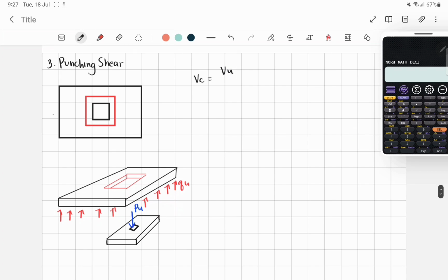Okay? So to get the punching shear stress, again, since shear yung usapan natin, that is VU over the shearing area. But ano nga ba yung VU natin dyan? Okay? So we can select from these two members to use. Kasi sa two members na to, when we analyze them or get our shearing force, equal lang yan. Okay? By the law of equilibrium. So for this member, itong part ng member na to will have a VU that is upwards. Okay? If we have this member naman sa mas maliit na part, edi downward siya.